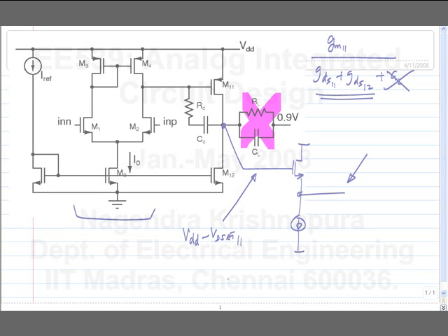Just like when you go from a differential pair to telescopic cascode, your frequency response remains more or less the same. There are of course some additional poles. If you replace this input circuit with a telescopic cascode, again, you are more or less set. Your stability criteria is almost always satisfied. Of course, you still have to take into account the parasitic poles in the telescopic cascode, but usually that's not a big deal. So, if I want to increase the gain, I would not try to increase the gain of the second stage. I would try to increase the gain of the first stage.